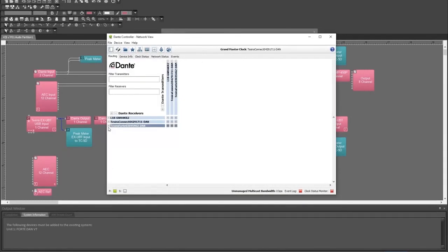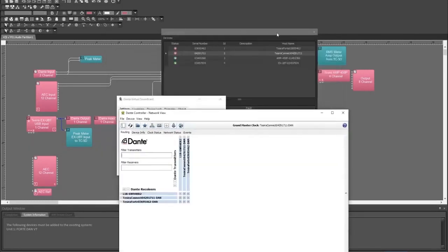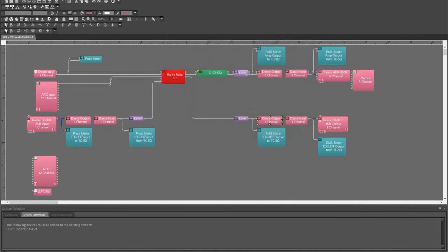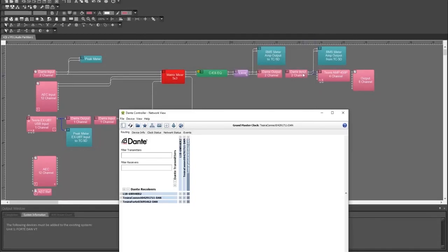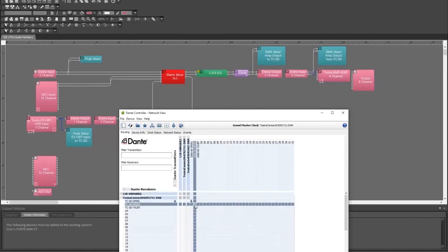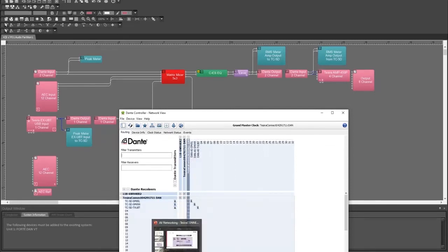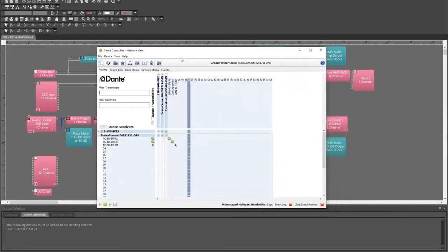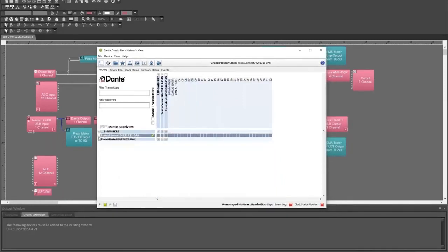Here I can spot all my devices. So now I have the input, the receiver blocks on my TesiraCONNECT. So I'll go into my TesiraCONNECT here. It's already labeled. The channels have been labeled when the block was added, and it's receiving audio from my Tesira Forte. So I will route the matching channels. It comes up green, so that is done.